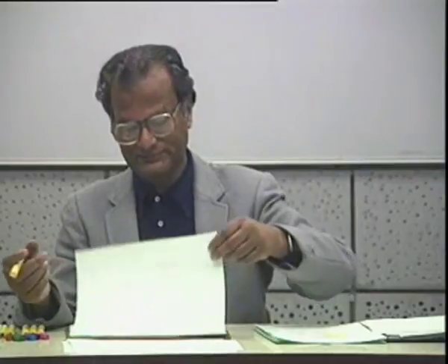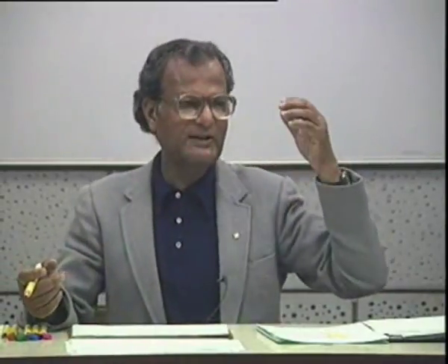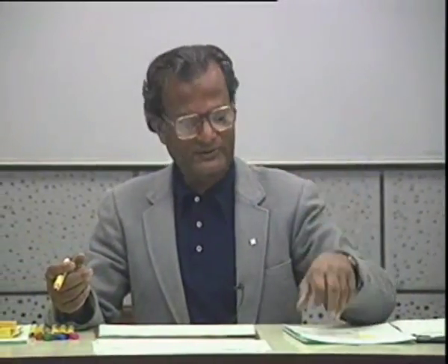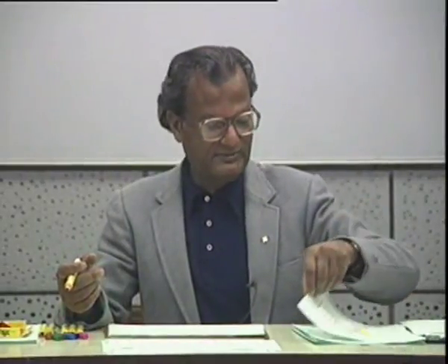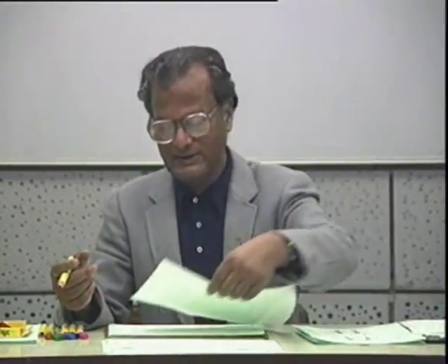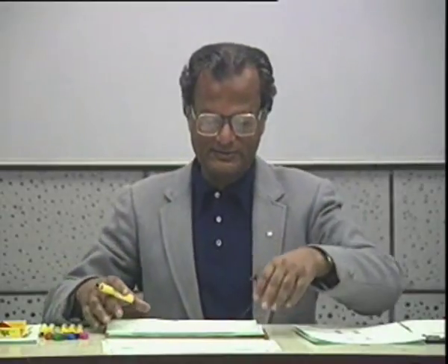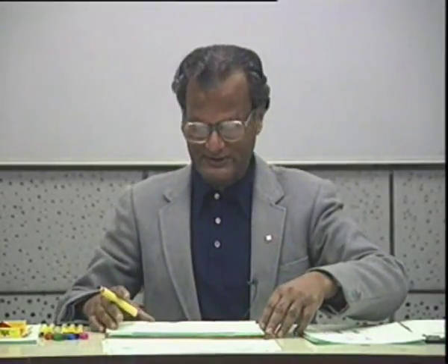Is that clear? So if the FET input impedance is very high, then what do you apply? You apply a voltage source. So it is voltage controlled. FET is said to be a voltage controlled device, whereas a BJT is a current controlled device. Although you get voltage amplification or current amplification from both, the basic mechanism is that FET is a voltage controlled device and BJT is a current controlled device.